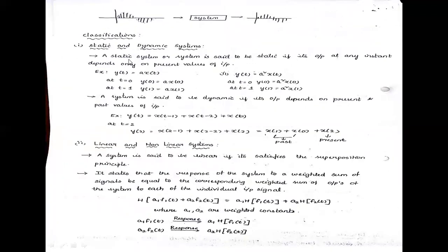What is a static system? A system is said to be static if its output at any instant depends only on the present values of the input, x of n only. So x of 1, x of 0, x of 2, and so on. Let us take x of t minus 1, t minus 2 and x of t. If it also depends upon past inputs, then definitely we can say that it is dynamic. A system is said to be dynamic if the output depends on the present and the past values. Static depends only upon the present, x of 0, x of 1, a constant value, the square x of t,